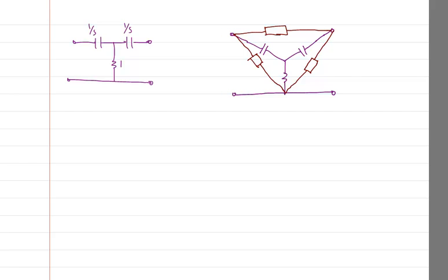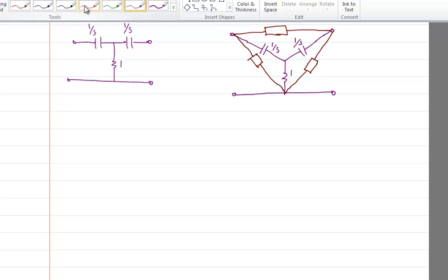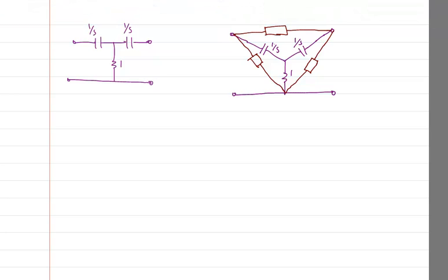And you all must remember the star delta rule, which says that, suppose this is 1 by S, this is 1 by S, this is 1. Okay, so here this value, let me take a different color. Yeah, this value will be these two components added up, which is 1 by S plus 1 by S, correct, plus these two multiplied, which is 1 by S into 1 by S, divided by the third branch, which is this one.